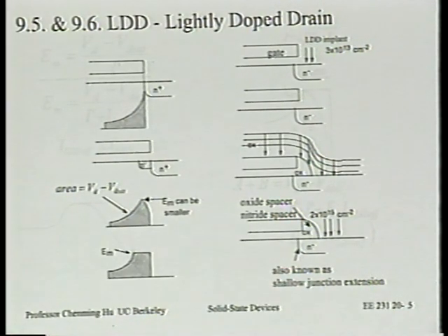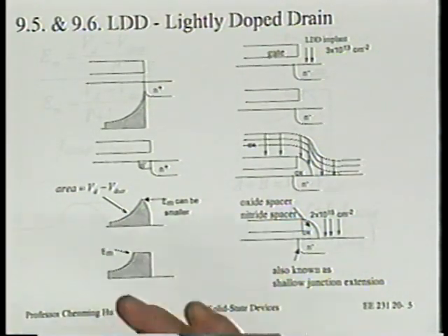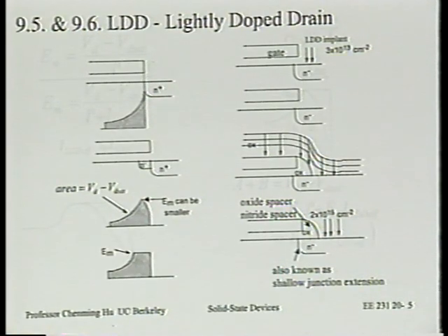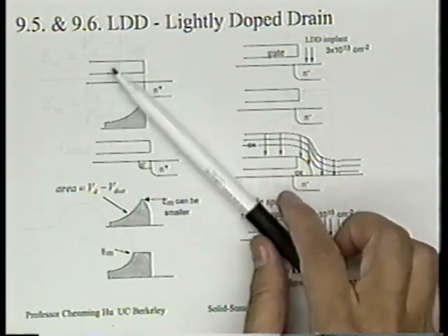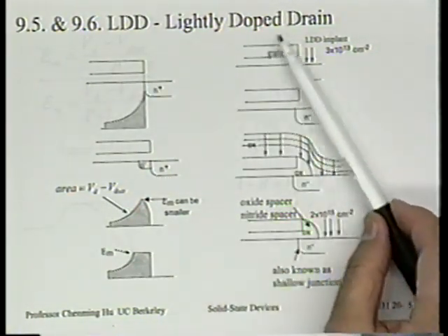It's interesting that early on, some 10 years ago, you still see people using the terminology conventional transistor as opposed to LDD transistor. And that's how people studied these two different transistors, LDD transistor versus conventional transistor. It's funny because certainly today no one will consider LDD as unconventional, and in fact we don't see any transistor other than one using LDD. So what does LDD stand for? LDD stands for lightly doped drain.